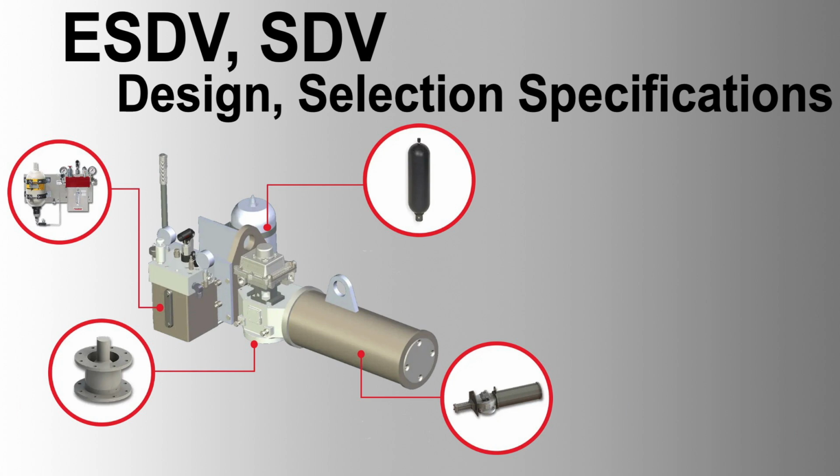Shutdown boxes. Components: solenoid valves, reset and local trip buttons, filter regulators, speed control valves, bypass valves, pilot valves, pressure gauges, and necessary tubing and fittings. Ingress protection: IP66. Material: heavy-duty SS316L enclosure. Cable entries: 4 ISO M20 by 1.5 cable entries. Mounting: must be mounted at an accessible location on the actuator.